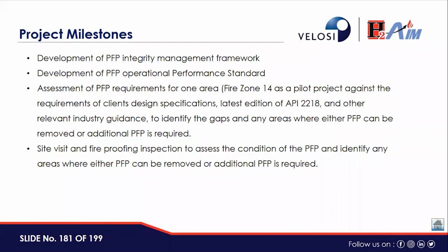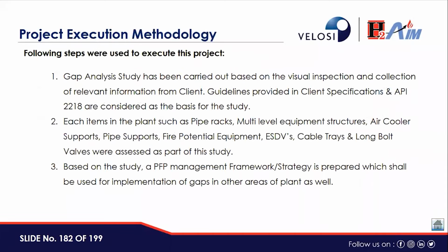Then the project milestone was the site visit and the fireproofing inspection to assess the condition of PFP and identification of any areas where either PFP can be removed or additional PFP is required. So the following steps were taken for the execution of the project. Gap analysis study has been carried out based on the visual inspection and collection of relevant information from client. Guidelines provided in client specifications and API 2218 are considered as a basis of this study.